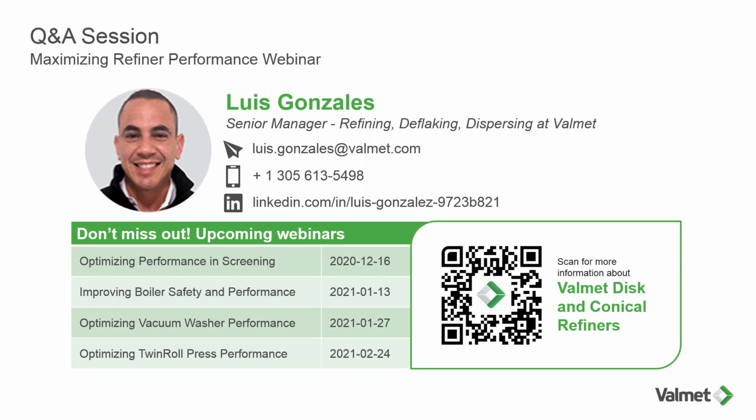For linerboard applications with virgin kraft, you're probably looking more like 5 to 7 years for a total life of 10 to 14 years. And then for bleached application, it's pretty much endless. We've seen installations where we've had these for 15, 16 years, and the customer hasn't even flipped the components yet because there's no wear shown on any of the spline components. It's highly dependent on application.